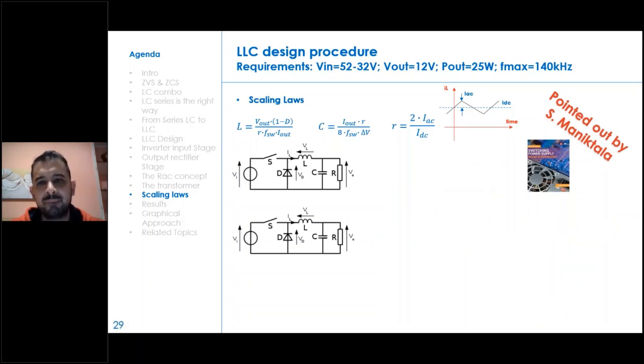What about the frequency? The same. These are the 2 formulas. If the second buck has double the frequency, I am placing a 2-factor here. So to keep this equation an identity, I need to halve this inductor. Same concept here. I'm placing a 2-factor, let's say an X factor, in the denominator of the capacitor formula. So to keep this equation an identity, I need to place a 2 here, so the capacitor should halve.